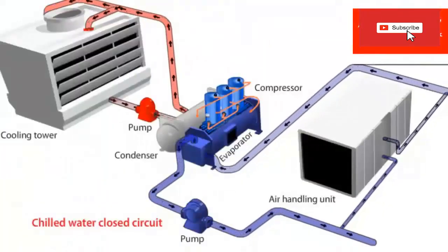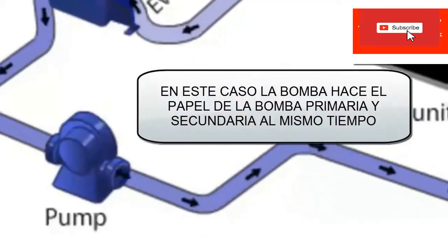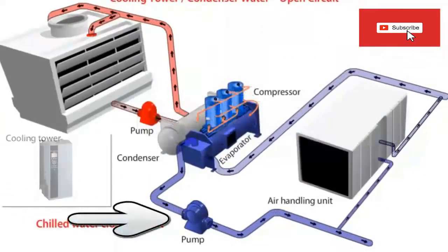In some more modern chilled water plants, the primary and secondary pumps have been unified in a single pump room that is responsible for performing both functions. Mostly these types of facilities have inverter-type controllers to change the frequency of the pump motors and vary their speed.